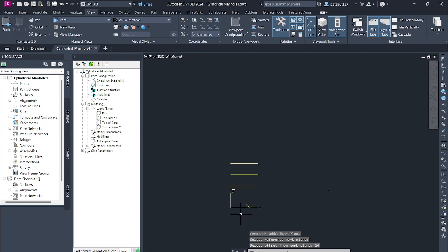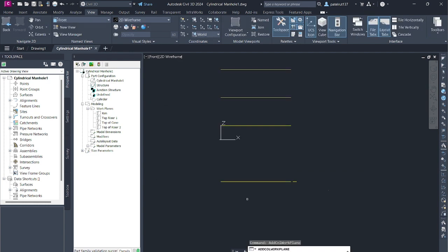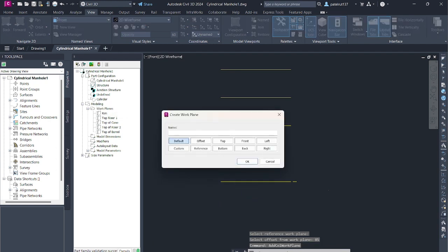Next you map each body diameter dimension to a corresponding structure diameter parameter. Using the calculator tool in the Model Parameters dialog box, set the equation column for each body diameter parameter making the following matches. BDYD1 equals SFD. BDYD2 equals SFD. BDYD3 equals SFD. BDYD4 equals 2 asterisk SFD. BDYD5 equals 2 asterisk SFD. BDYD6 equals SID. BDYD7 equals SID.